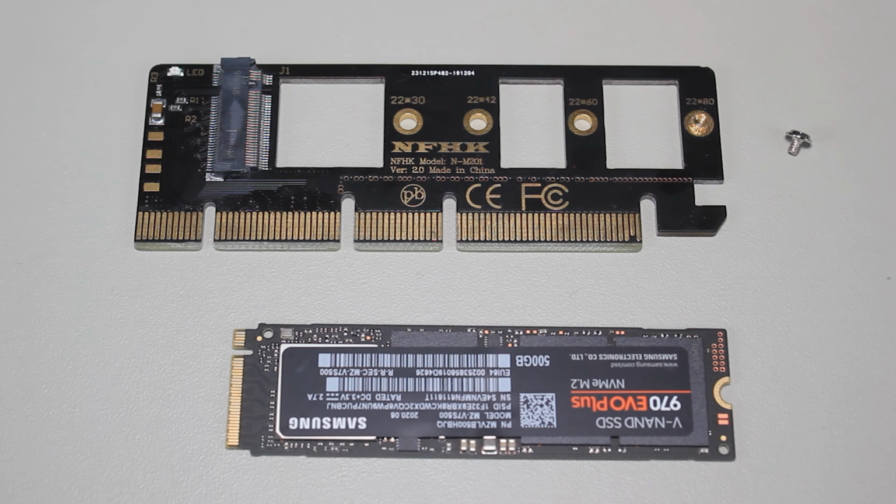The board is very simple in design. It basically connects power and PCI Express lanes directly to the M.2 device. Thus, if you plug an M.2 SSD in that does not support PCI Express, it will not work. Although it is possible for an M-type board to support PCI Express and SATA, generally they only support PCI Express. If I attempt to plug a B+M board in, it most likely would not work. The reason for this is these boards tend to only support SATA.